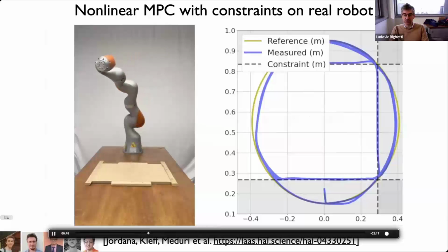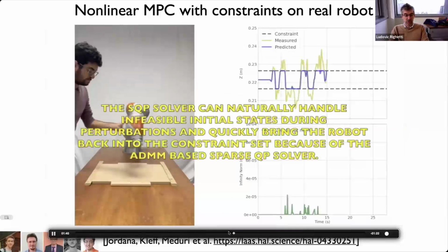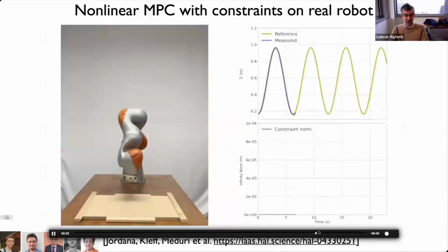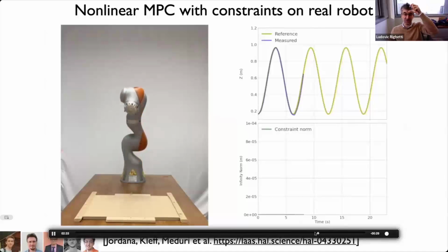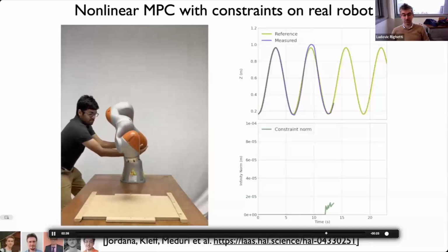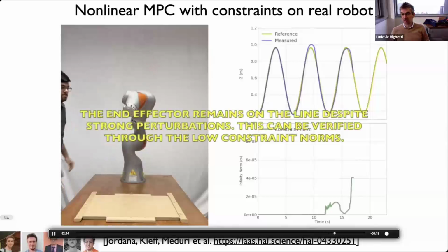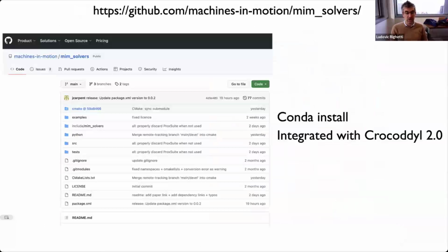So here it's really an exact mapping from measurement, to MPC, to torques, and nothing else, right? There's nothing in between. And this actually works really well. And then you can start to do other things. For example, here's an example where you force the system to be on a vertical line, going up and down for the end effector, and then you can start abusing the robot, and the robot will always try to satisfy these constraints. So you will get this kind of behavior, which I think is not trivial to get online, but you can actually do that by doing this solve.